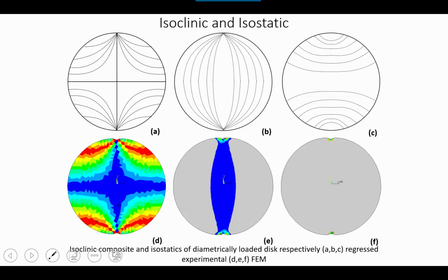So overall, this shows that we can use the theory of elasticity. We can also apply numerical methods, or we can experimentally determine these stress field and strain field equations and subsequently figure out what the stress concentration factors are. Really, the best approach right now, the modern approach, is to design a well-posed finite element model, and then we can figure out for complex loading conditions what our stress concentration factors will be.